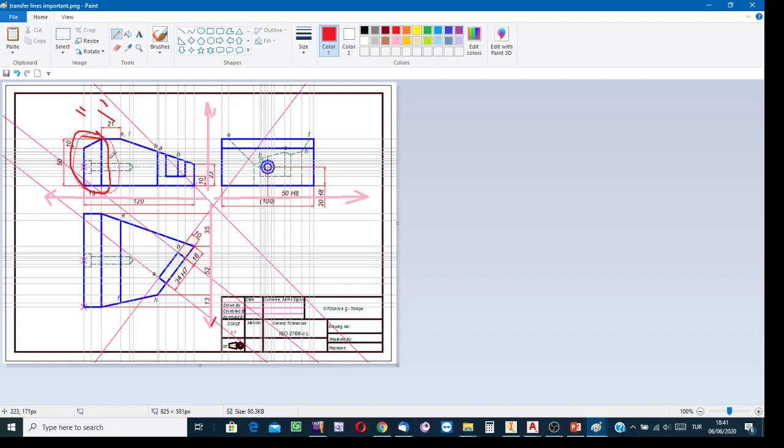Since the views are consistent, following those transfer lines, this and that, on the other side image, between the same two transfer lines, we must find the other side image of the selected feature. Thereafter, we can combine this view of the feature with that side view.